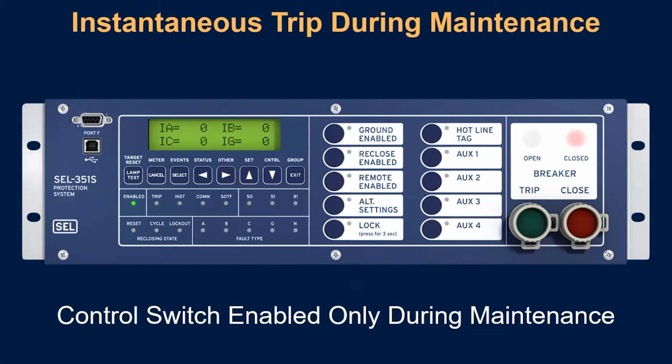for the apparatus that we're performing maintenance on. We can enable that instantaneous trip just while I'm performing that maintenance on energized conductors. In utility spaces, this is commonly called hotline tag, right? So some of our relays will have a button dedicated for this purpose on them. In a lot of industrial spaces, I hear this referred to as maintenance mode. But either way, we can use push buttons, programmable push buttons on the relays or inputs on the relays, and bring that push button or optical input into the programmable logic offered in SEL relays to provide supervision.